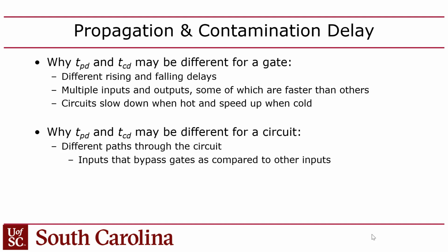So, but anyway, there's differences. Temperature affects it also, but with a logic circuit, typically when you talk about a logic circuit, you're talking about multiple gates, right? And there's multiple paths through that logic circuit. So sometimes you might change an input that has a short path, and sometimes you'll change an input that has a longer path, because not all the paths in the circuit are balanced. So that's why those may be different.